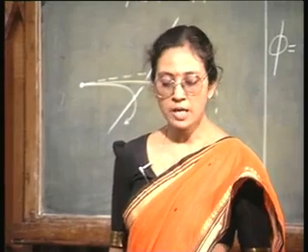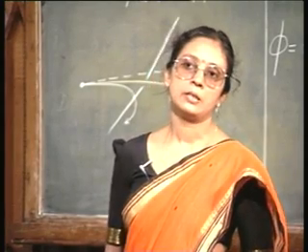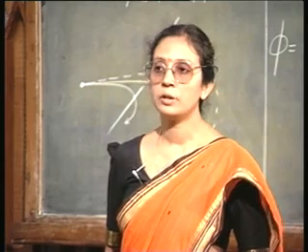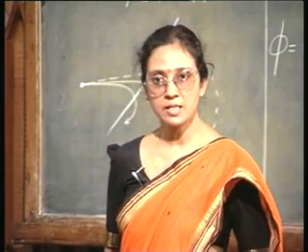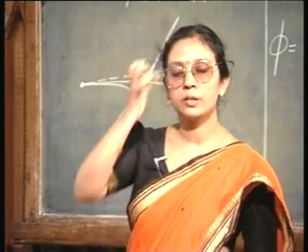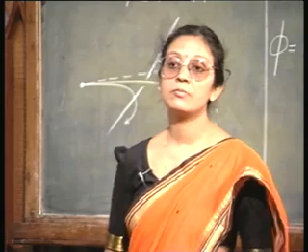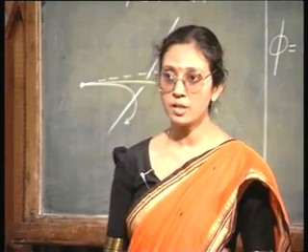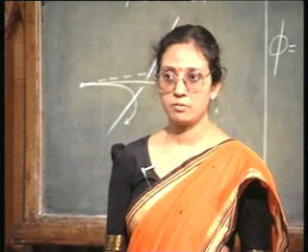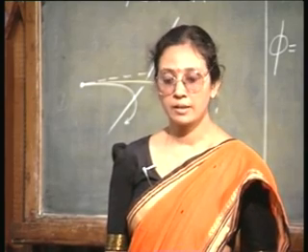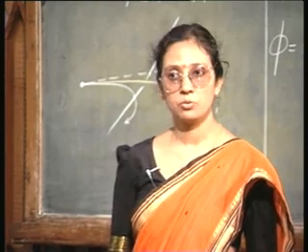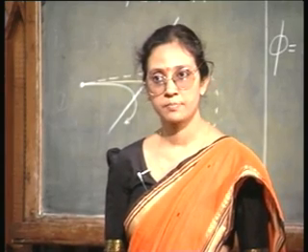And of course, how deep the dopant is going to go, that will depend on its energy and on its mass. If the dopant ion is light, then with a relatively less energy it will go much deeper. If the dopant ion is heavy, then it will need comparatively greater energy in order to penetrate to a comparable distance.